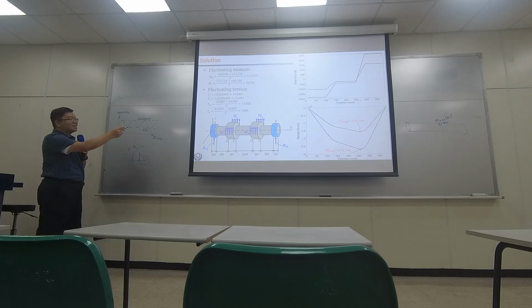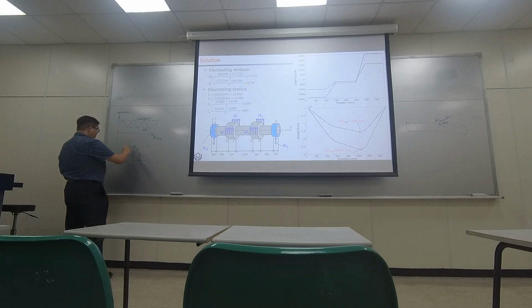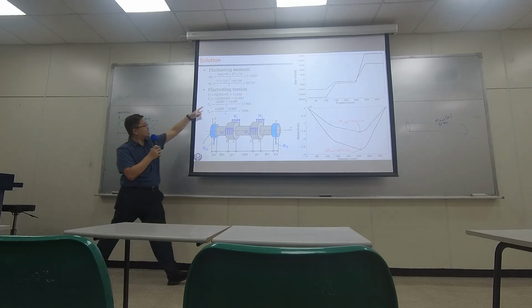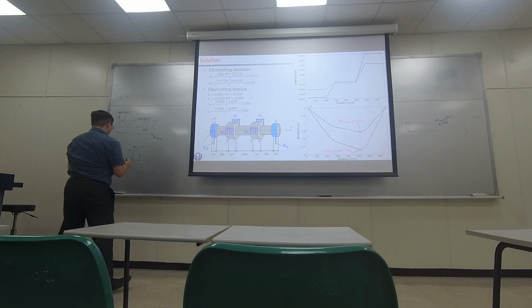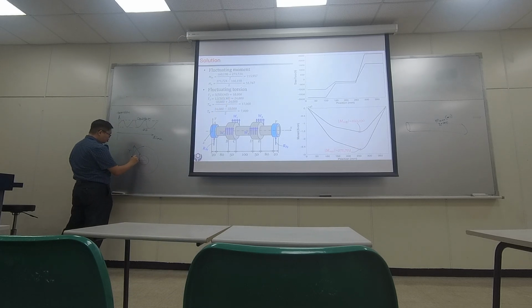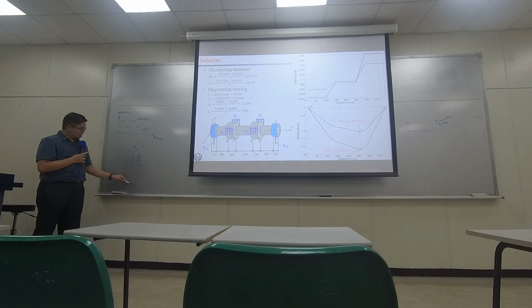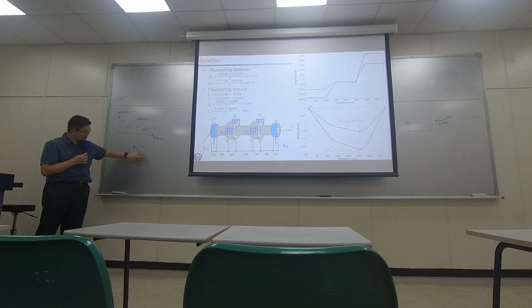So if this is the amount of torque, like the value I computed, then I should use this smaller one, because if I assume the torque is linearly distributed inside the shaft and the pulley itself, then the torque should be slightly smaller.